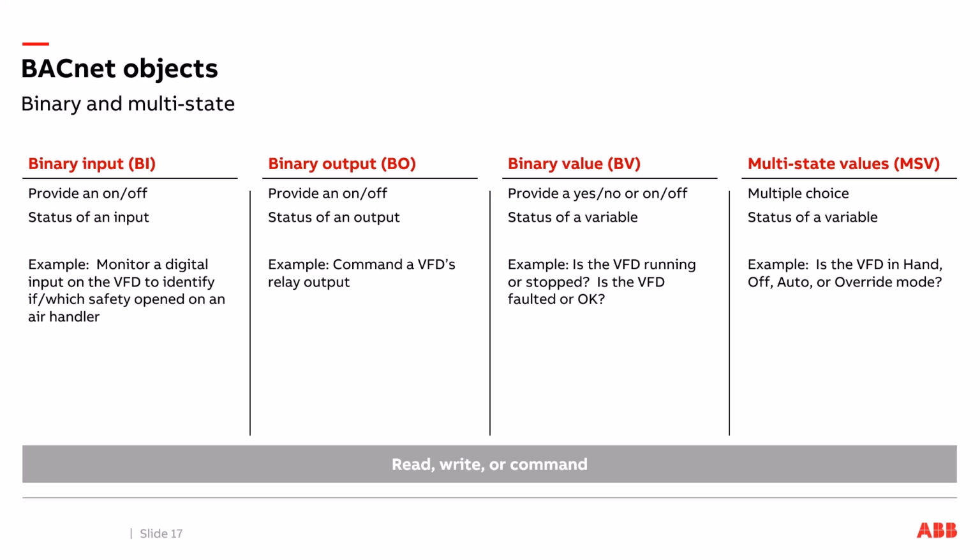So for example, I can monitor the digital inputs on the drive and I can see each of my digital inputs. Is it open or is it closed, on or off? Really handy, for example, if I have a supply fan application, driving a supply fan, I got a high static safety, I got a smoke alarm, and I got a freeze stat safety all wired into that drive. Yes, I'm in Wisconsin. We have freeze stats. You don't have to worry about that in southern parts of the U.S.